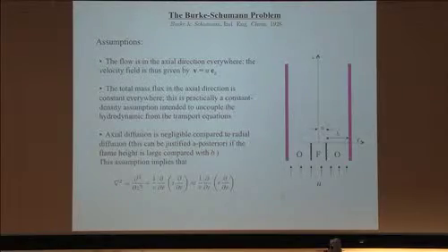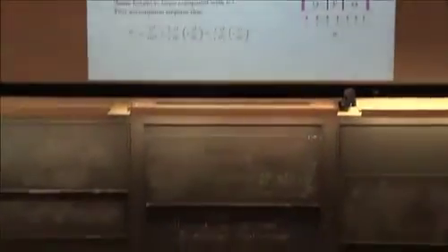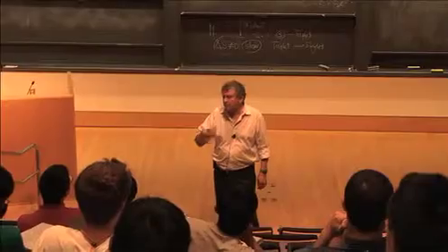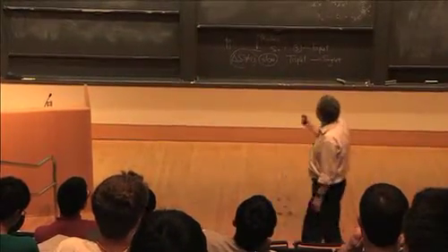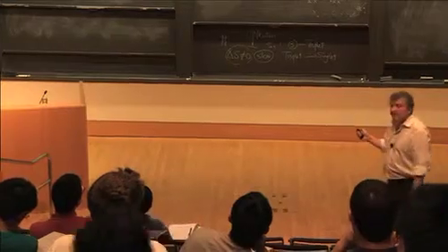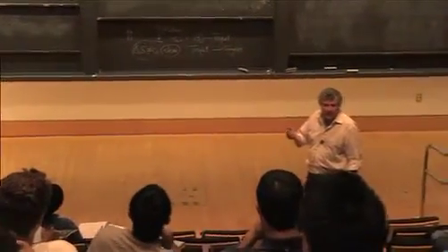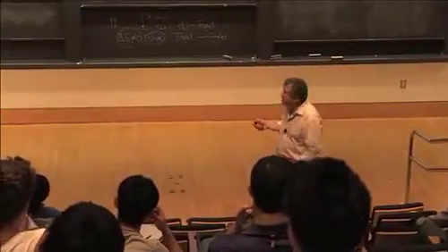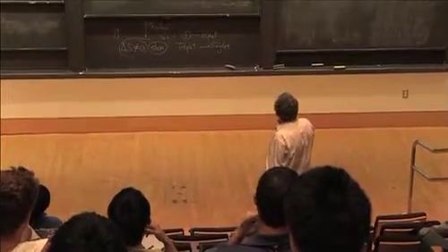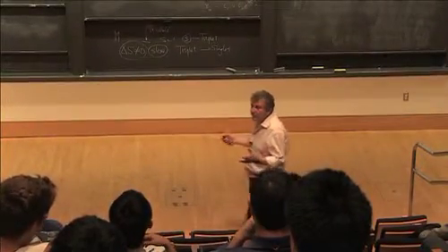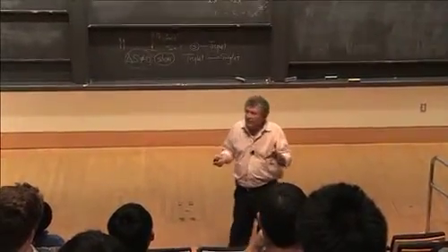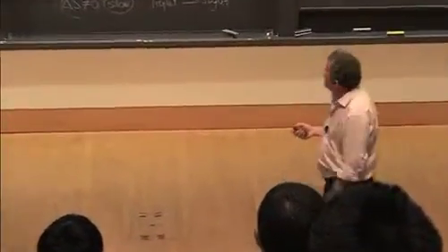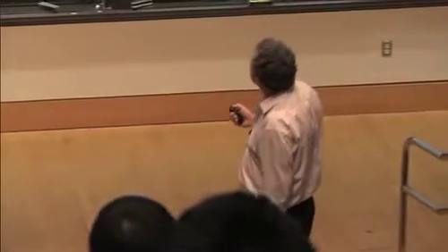Usually it will change because the density changes with the temperature, and the temperature increases as a result of combustion. So essentially they have assumed a constant density assumption, even though it was not explicitly stated. It turned out that in diffusion flames, it's really less dramatic than in premixed flames. But anyway, that's a side comment.